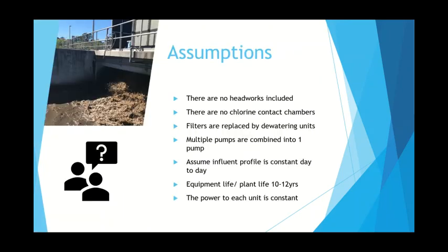The assumptions that we made in modeling this process are that there are no headworks included because it cannot properly be modeled in BioWin. There are no chlorine contact chambers because they cannot properly be modeled in BioWin. Filters are replaced by dewatering units because of the data that is available.